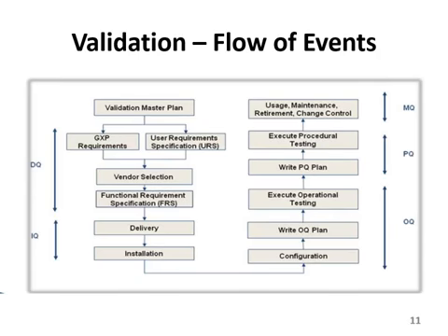So after installation comes OQ, that is operational qualification, or operation qualification, where you are going to start the operation on your machine. After installation, you have configured that everything is okay, and you are settled with the machine or equipment, and then write the OQ plan, how to operate it. Write it down. It will be easy. It will be not only easy, but it will be better for the machine and for yourself and for the process, all the things.